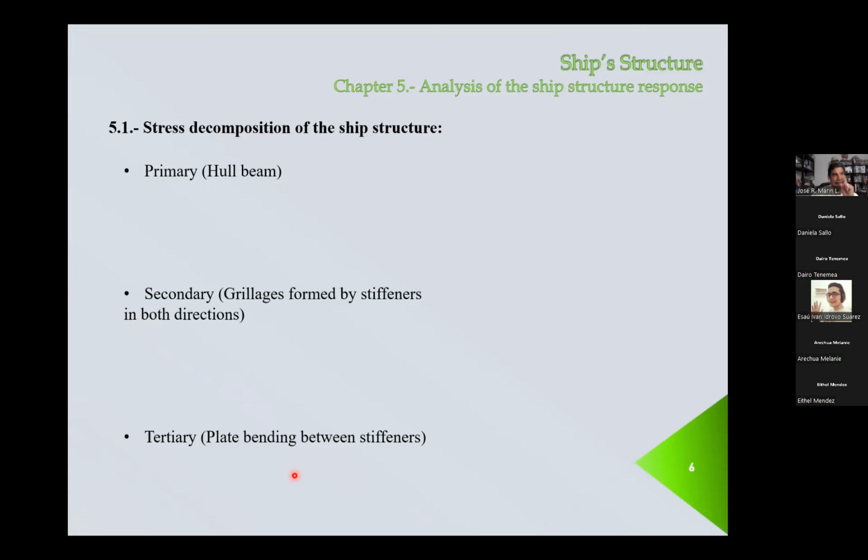If they were clamped, then the bending moment close to the boundaries, the edges, will be about twice the value at the center, when you have a uniformly distributed load, more or less. But when you have this redistribution, because the stiffeners bend a little bit, you have about the same stress on the side as at the center. They have different sign, remember? The curvature is like this and like that. More or less, the values are about the same.